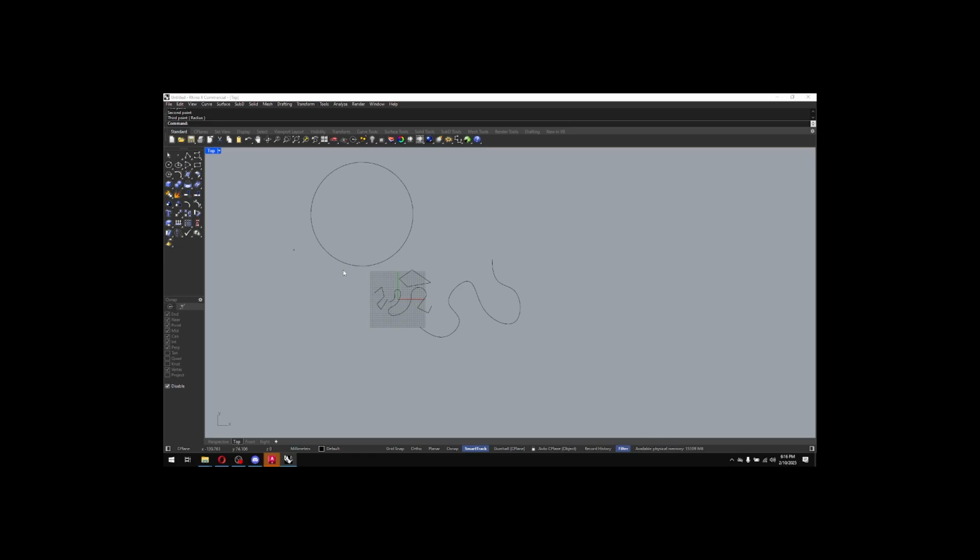Rhino, which is different from things like 3ds Max, if you've ever used that, or a lot of other modeling software, calculates sizes and shapes of things based off of curves and surfaces rather than meshes. Again, you don't necessarily need to know what that is, but what's nice is it keeps your file size small. When you export, everything gets converted to meshes anyway, but it's a way to produce very accurate drawings without overloading your computer with triangular meshes.